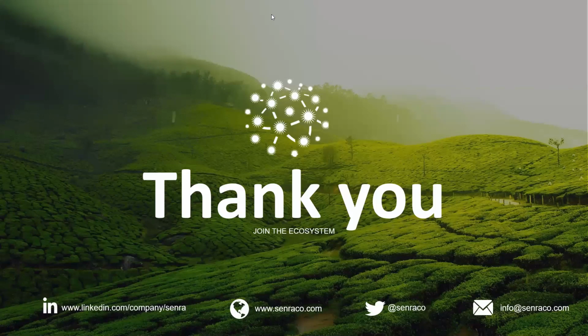Cool. So let me see if some of the questions are there that are really easy and we could answer them right away. What's the difference between LoRa and LoRaWAN, Zoya? That is something that we discussed thoroughly in the previous webinar. Note that LoRa is a physical layer protocol. And one of the prominent features, one of the prominent beauties of LoRa is to do the modulation that we understood today. All the things that are related to adding network related fields is part of the MAC layer, and that is actually LoRaWAN.